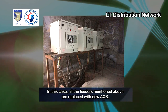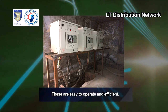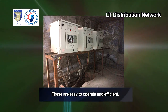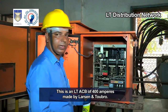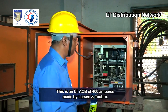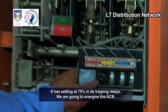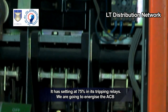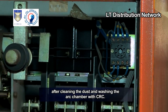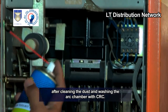In this case, all the feeders mentioned above are replaced with new ACB. These are easy to operate and efficient. This is an LT ACB of 400 amperes made by Larsen and Toubro. It has setting at 75% in its tripping relays. We are going to energize the ACB after cleaning the dust and washing the arc chamber with CRC.